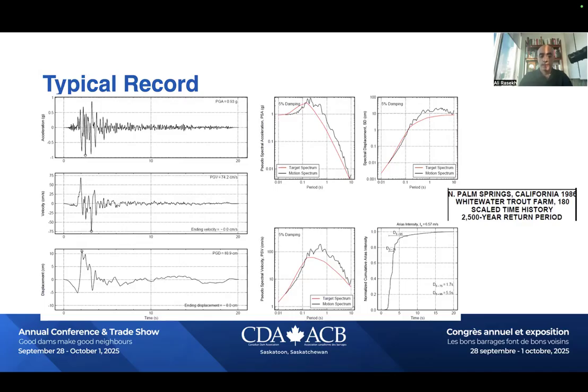We can create the acceleration response spectra for the record and compare with the design spectra. I can tell you that almost every single time I find that I should ask for modifications. And the one time that I didn't ask, I was in trouble. So this is the most important sanity check that we should perform as structural engineers who are using those records.